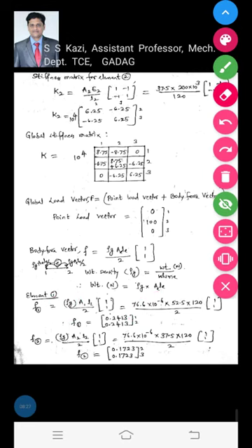Since the given value is already in Newton per mm cube, you directly substitute that value, no need to convert. Next, the area of the element is 152.5 and the length of the element is 120. If you calculate this ratio, we get 0.2413, so inside the bracket I wrote 1 1 into 0.2413. For the DOF numbers you write 1 2, because element 1 consists of two nodes, 1 to 2.